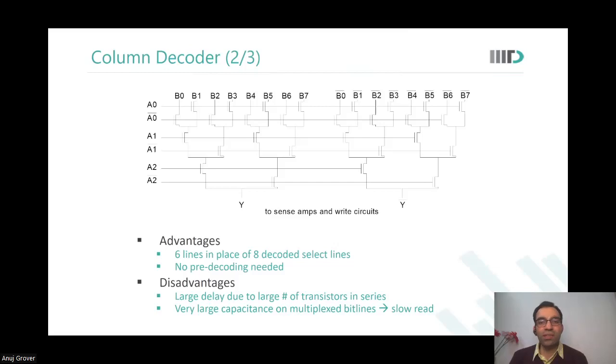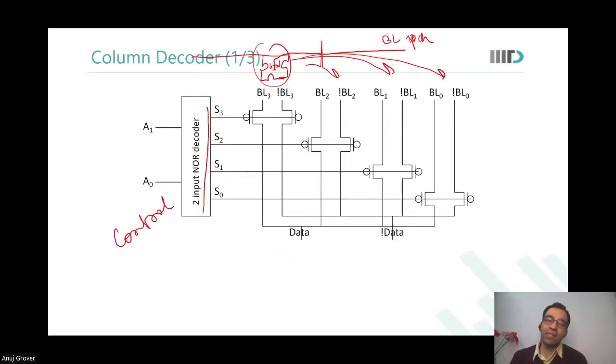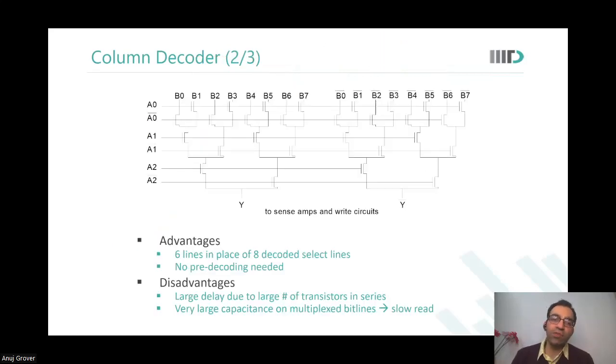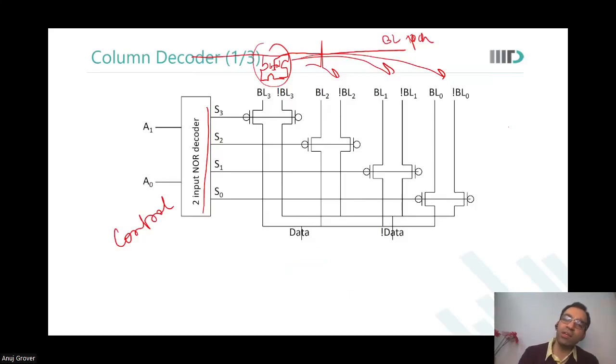So what is the limitation of this one? Here you saw that there is one stage, and in this your MUX4 is implemented. Yes, NOR type of decoding. There is another kind of decoding which is called tree decoding. And over here what is happening is that you implemented MUX8. If I have to implement MUX8 using this kind of a decoder, how many select lines do I need?